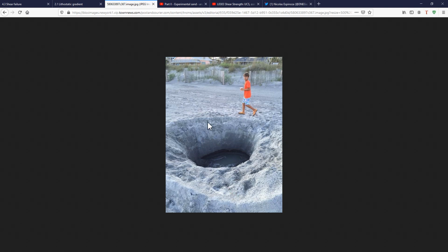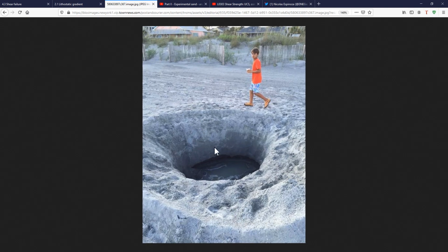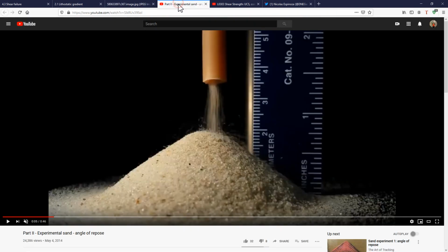If you have just sand, dry sand, as for example you might find on the beach, on surface you're going to see that this sand doesn't have any strength, and therefore because it doesn't have any strength, you can move the grains with respect to each other and nothing is going to hold them together. This is what happens if you make a pile of sand, the grains just roll on top of each other, and on the surface they are not going to have any strength.